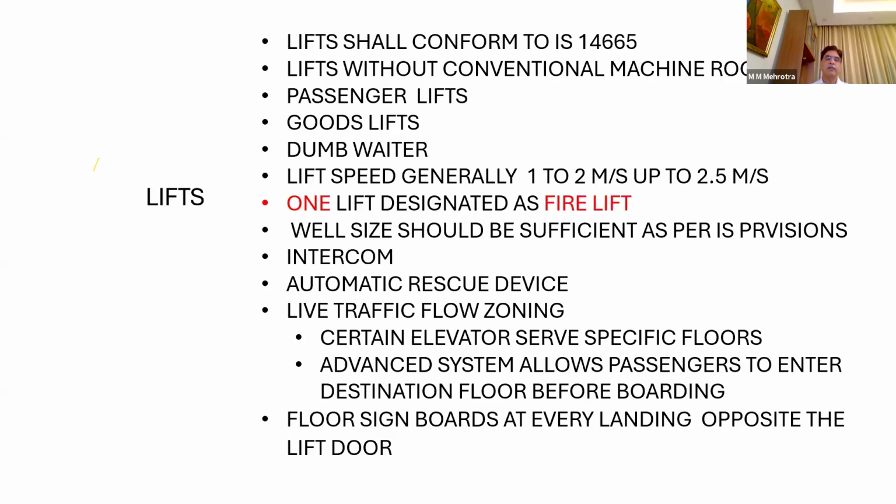When we give a command to that lift, supply comes into the brake and it releases the rope. Then the lift is free to move. Suppose there is a power supply failure, what will happen? That brake will immediately be applied onto the rope. Now the lift cannot move.